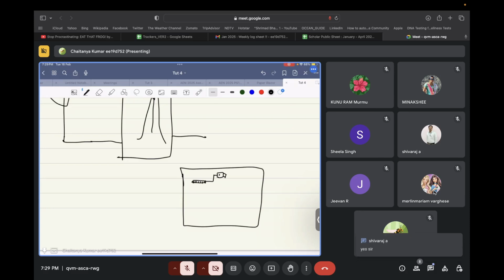So basically, what is a CMOS? MOS is metal oxide semiconductor. So metal is a conductor. Okay. Then you have an oxide, and what is that oxide made of? Can someone comment? So this is a metal, SiO2. Okay, silicon dioxide you have, and below that you have this silicon substrate. Silicon also, if you dope it, becomes a conductor or a semiconductor. So between two conducting plates, you have an oxide, an insulator, and that will behave as a capacitor. So capacitors also are easy to make on a wafer.